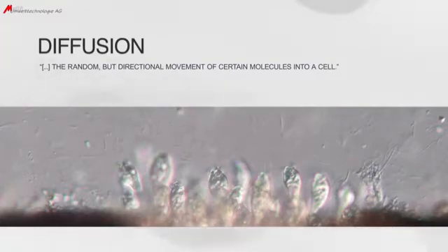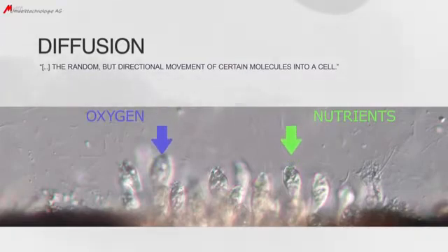The diffusion effect in biofilm processes has to be understood as the feed of substrate and oxygen molecules into the active biomass. Nutrients, like for example phosphorus as well as oxygen, diffuse from the surrounding water into the active biofilm and supply the microorganisms in the pores. In other words, diffusion is the supply of the biofilm or the microorganisms on the carrier with substrate and oxygen. Substrate refers to the pollutants present in the water which are to be degraded by the microorganisms. A sufficient diffusion is an essential factor for the removal performance of active biomass.